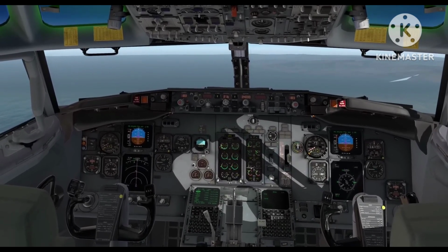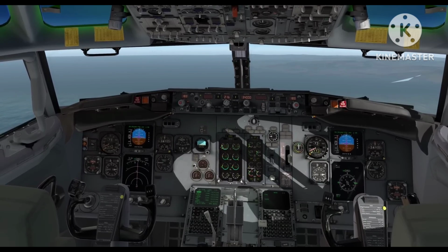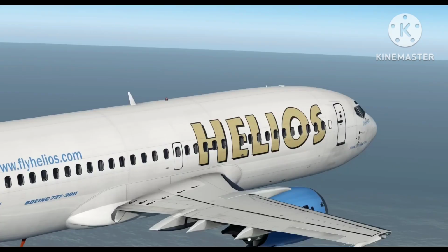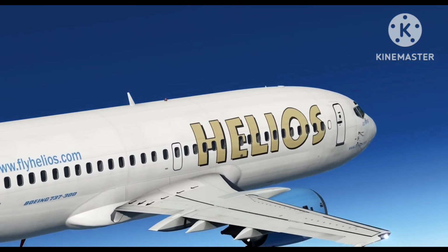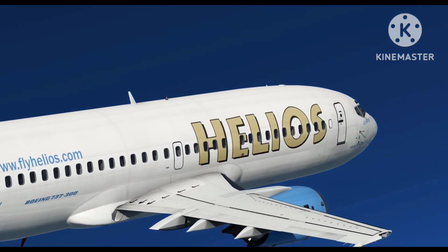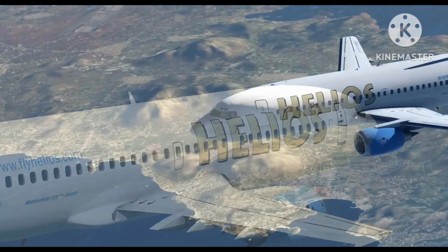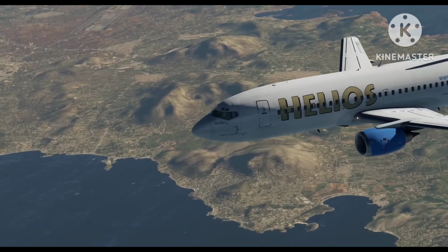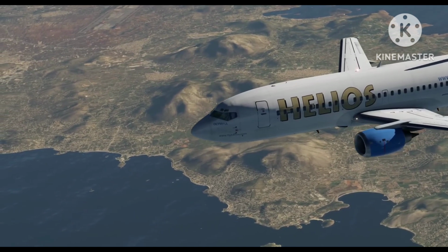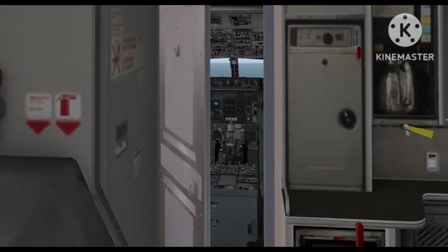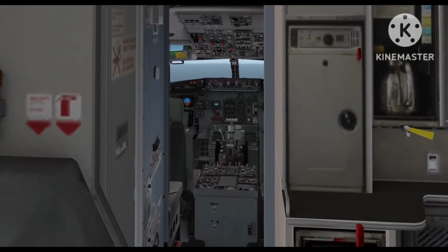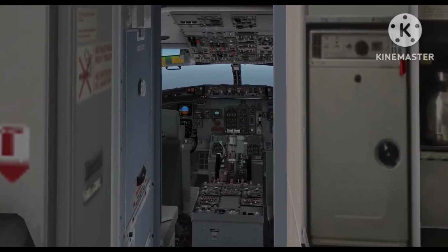During their pre-flight checks, the first officer was responsible for setting the pressurization panel. This included ensuring the pressurization mode selector was in auto. However, it's possible he overlooked this due to perceived time constraints or because he was familiar with the selector's usual position. The pre-flight checklist should have caught the switch's incorrect position, but it didn't. After completing their checks, the aircraft taxied and took off normally at 6:07.